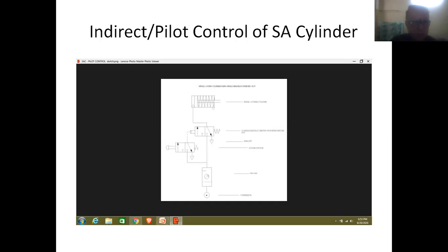So with the arrangement of ports in this particular fashion, the push button has to be placed in the right side of the pilot valve, and similarly the return spring has to be placed in the left side of the pilot valve. As usual, this push button will be fitted to the plunger that is arranged inside the body of the valve.